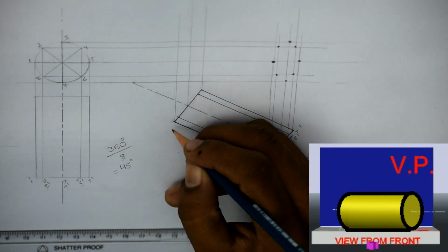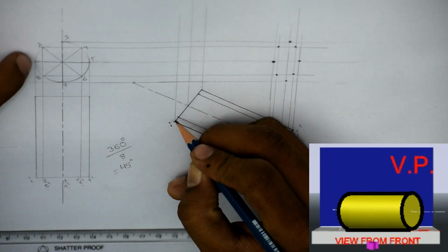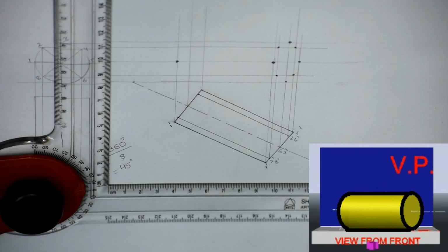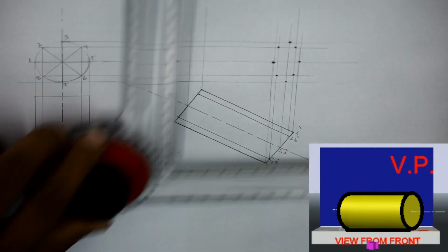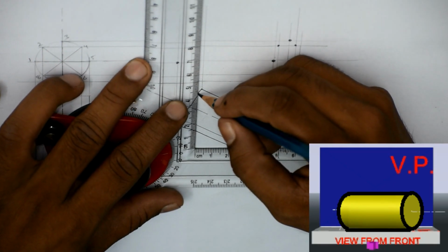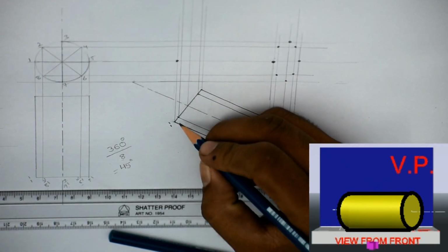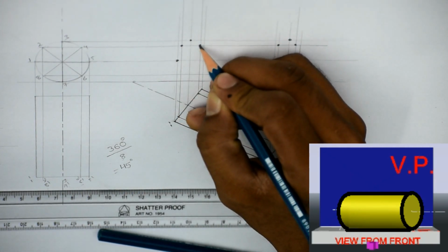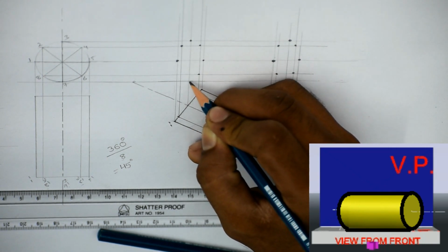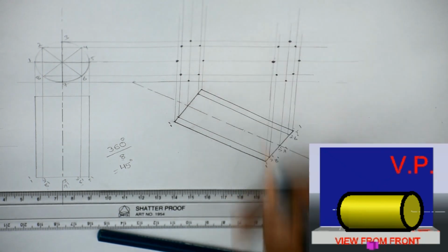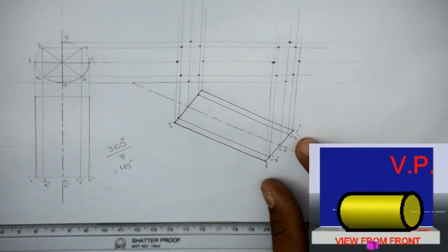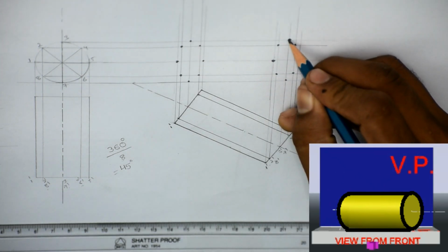And the same way, if I mention 1 dash here, this 1 will come from this side. So this will be your point. So this 2. Again I have points. So this line number 2 and this is line number 2. 3, 3, 4, 4, 5, 5, 6, 6, 7, 7 and 8, 8. And as we are viewing from the front view, this portion only will be visible completely, but not this. So I will darken this portion.